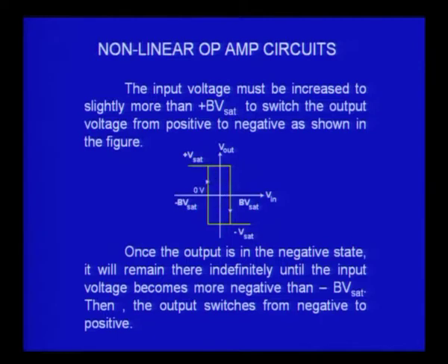Similarly, we get a device hysteresis behavior here, and therefore it is called hysteresis. The difference in voltage is what actually matters for us with reference to a comparator, and it is made this way so that it can be unconcerned about the voltages corresponding to the noise.